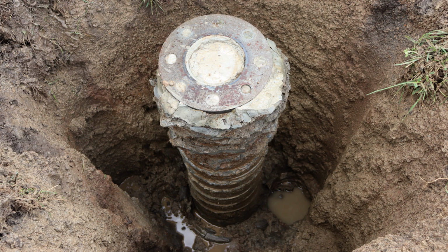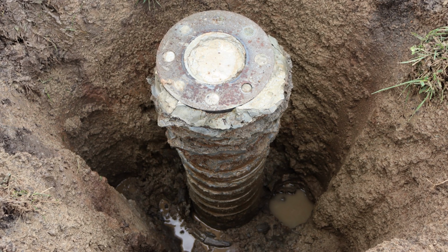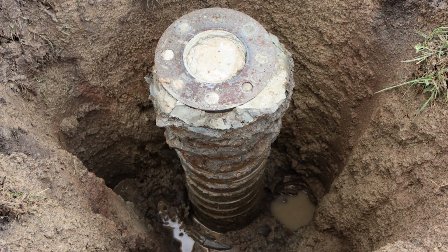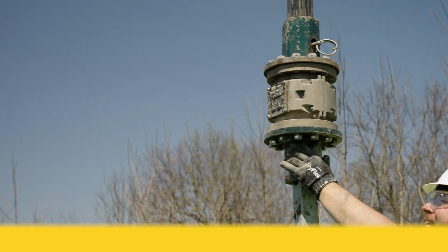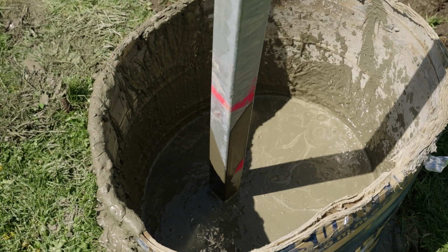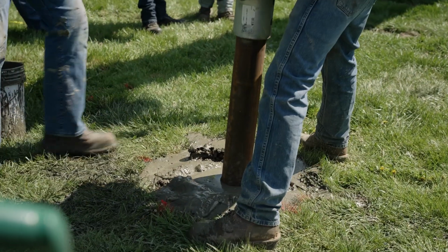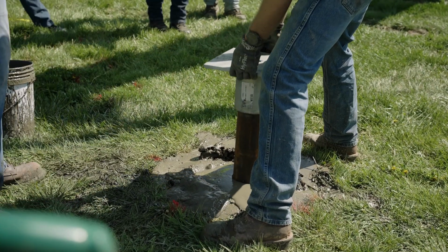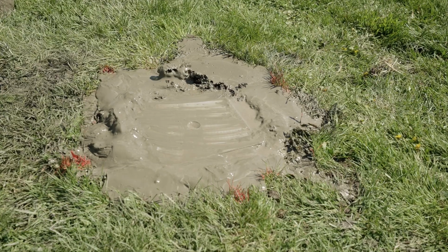The displacement casings and plates create a uniform, continuous diameter grout column. Unlike some other displacement pile products, you can expect a full diameter grout column with GroutForce. Continue adding extensions and grout until the minimum depth has been achieved. The GroutForce displacement pile connects to the structure using an approved Chance steel adapter or a pile cap capable of safely transferring the structural loads to the pile.